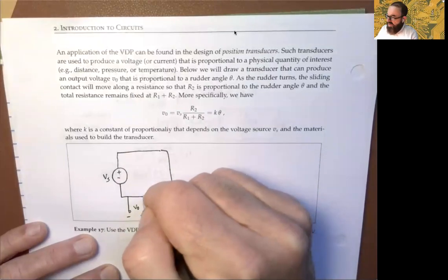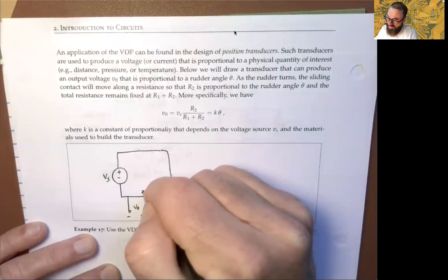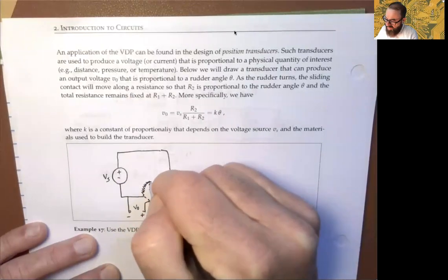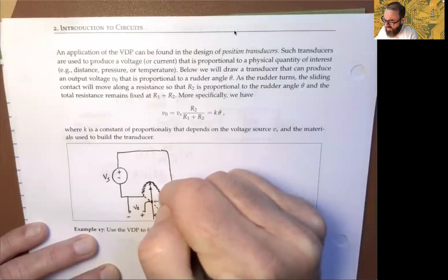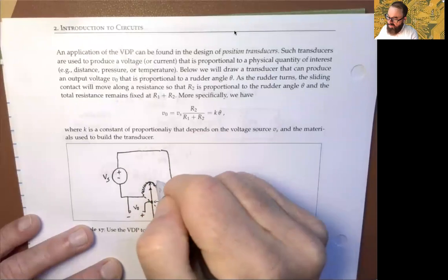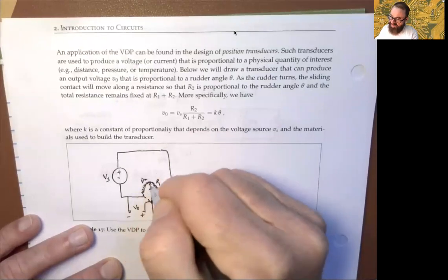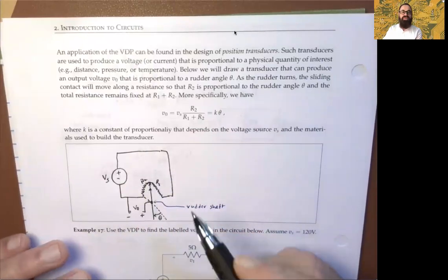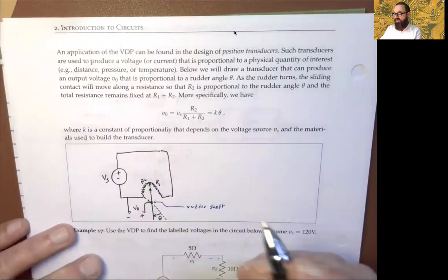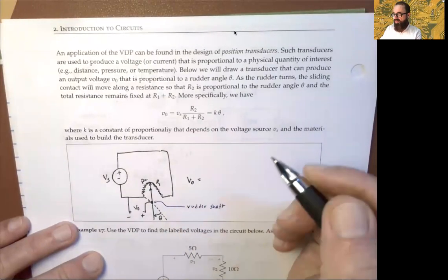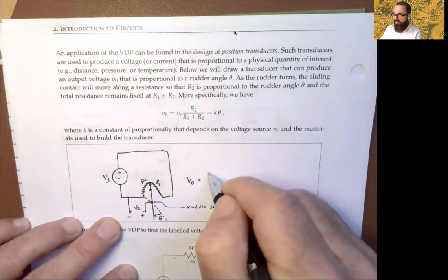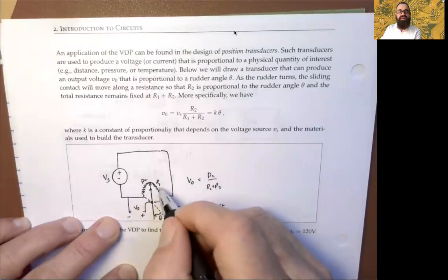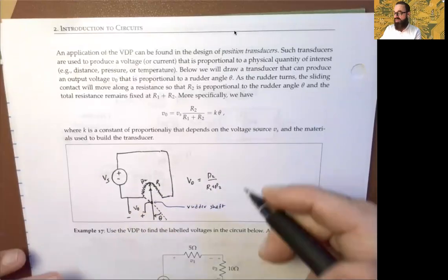And so the contacts are made with resistances. The resistances are end to end. This actually would come up and make a contact with it. And there are really two of them. The first part will be R1 and the second part will be R2. And so what happens as the angle turns, we're coming into the R2 portion rather than the R1. And so this illustrates that the output voltage would be a scalar form of R2 versus the total resistance given by the end-to-end resistances. So they're in series, end-to-end there.